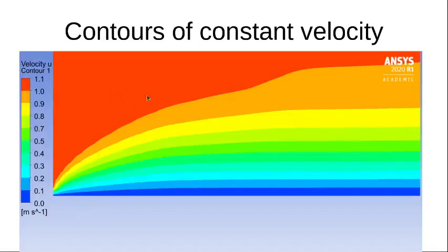So you can see that in this region, it's actually showing a velocity greater than 1. So there is some numerical error in this solution. That's also responsible for all this wiggly and wavy behavior. There's some numerical instability in the solution process, which I need to correct.